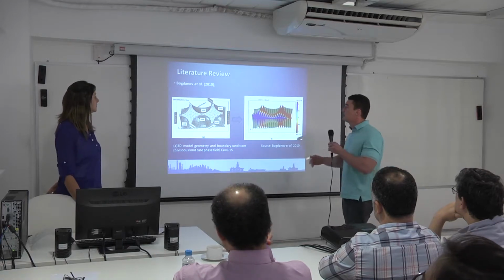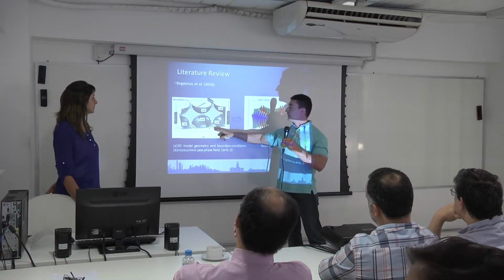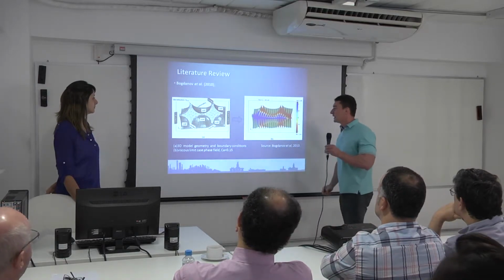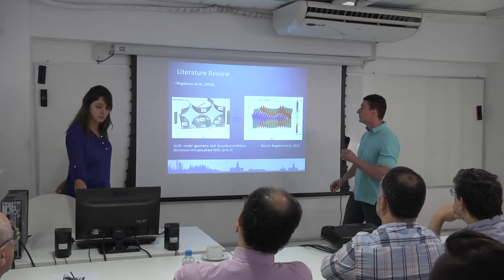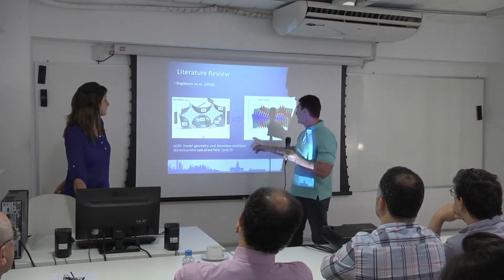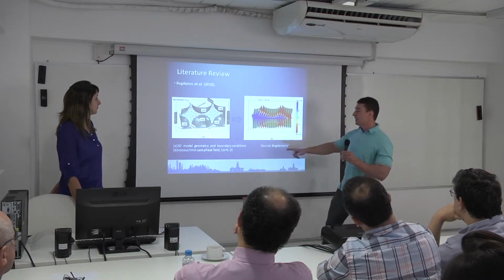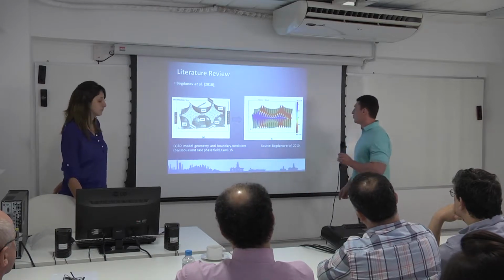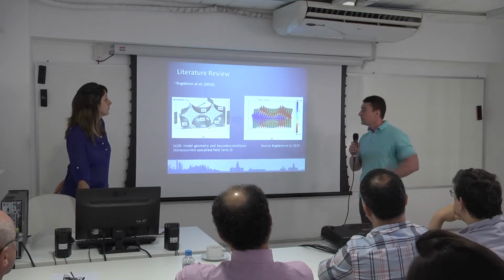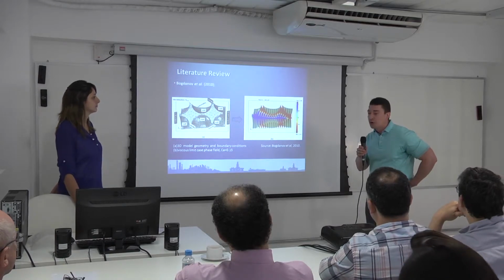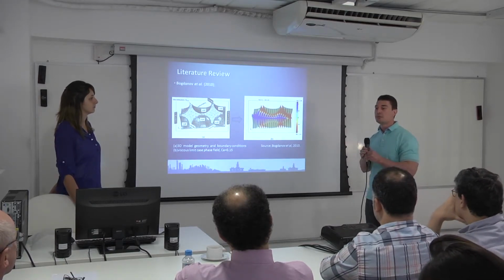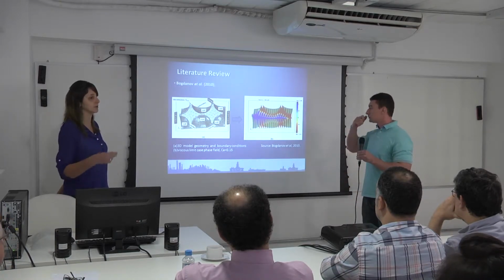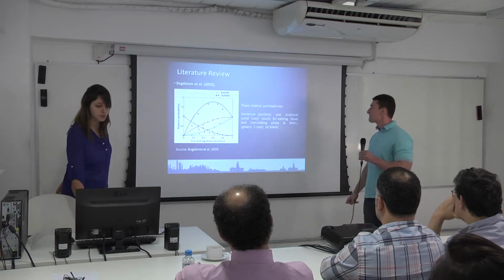So in this case, they create the geometry inside COMSOL itself. They choose what is inlet and outlet, and then they can create the boundaries of the entire geometry, and they simulate in COMSOL. In this case, the viscous limit case, where you have the capillary number of 0.50. So it's very interesting because it's the first time that they use COMSOL to do two-phase simulation. But it's not 3D, it's 2D. So I think we are going to be one of the first to perform this work.